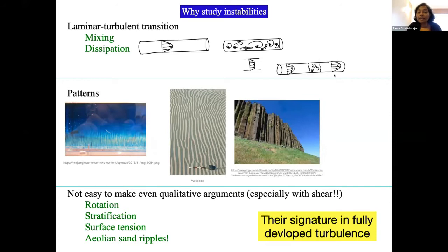Now, in intermediate Reynolds numbers, you can get turbulent puffs in the middle of a laminar sea. So this is the kind of insight you gain from studying instabilities. These streaks that I'm talking about, these long streamwise vortices and low speed streaks, which we'll talk about, are a very important result of instability, as we will come to, and they determine so many things, including shear stress at the wall. This is one reason to study laminar turbulent transition.